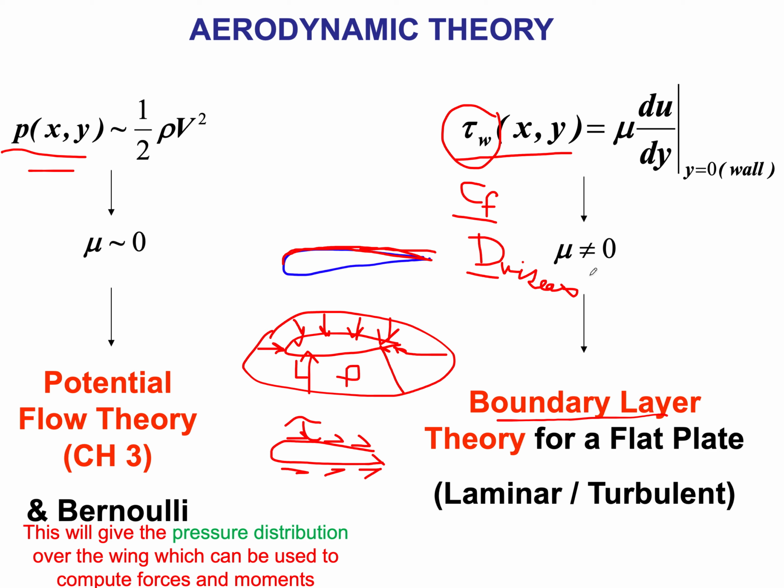I'm not going to tell you that the shear stress is going to be 2 Pascal, but I'm going to tell you it's not going to be 10 Pascal or 0.1 Pascal. It's an order of magnitude. I'm not going to be able to differentiate between 2 or 3 Pascals. The level of uncertainty is quite big, but in certain cases we might be able to get to an uncertainty of 10-20%. That's the best we can get to.